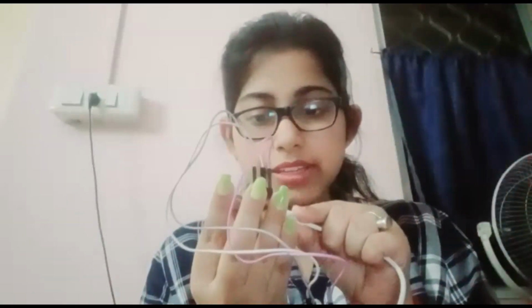Right, and last we are left with the ground pin of the LM35 sensor. So I need to take one more male to female jumper wire, insert it in the third leg of the LM35 sensor, and insert the other end in the ground port of my Wi-Fi module. That is all. Okay, so this is the final connection. I hope you can see. So I will use my USB cable, and I will connect this to my Bolt Wi-Fi module, and now this is connected. All I need to do is just insert this in my laptop.